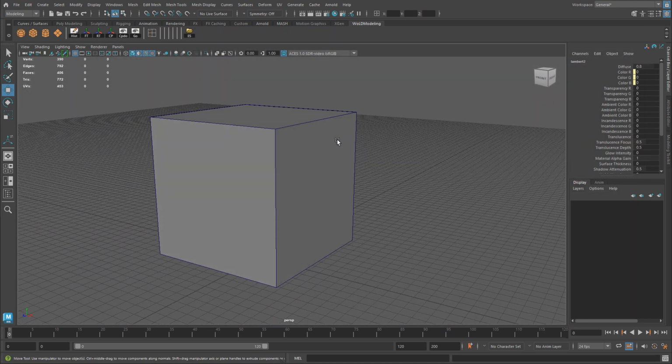And this is because you may have an icon enabled to view default material on. So if you come over here to the very top, this icon right here, this is what's messing this up. Right now it's enabled and it's using default material, which is Lambert 1. So I want to go ahead and disable this. Sometimes it gets enabled by default whenever you're coming over here.